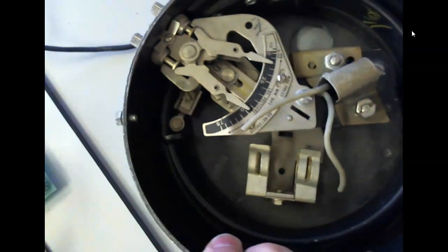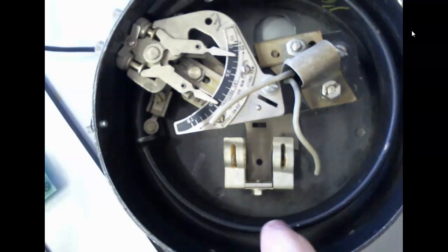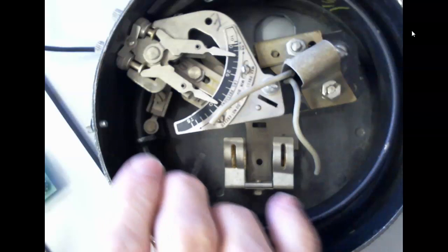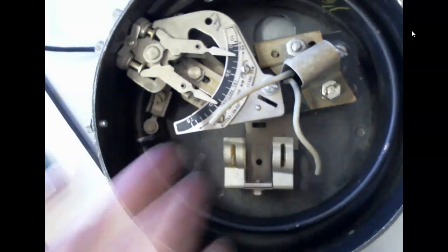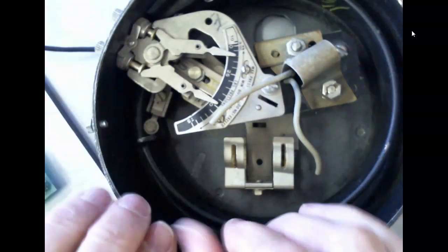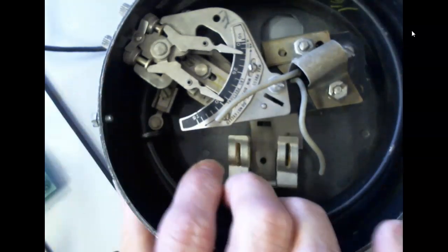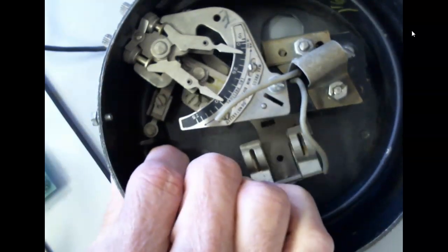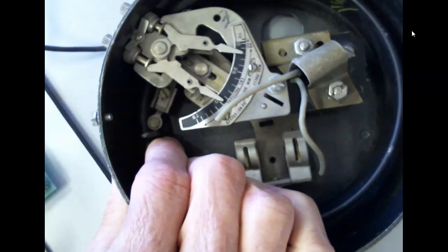What happens when the pressure comes into a helical bourdon tube is it would try to make it come out of the helix, unwind. A bourdon tube, by the way, can measure both pressure and vacuum. If we put a pressure on it, it's going to cause the bourdon tube to try to come out of that C that it's in. If we put a vacuum in it, it would cause it to try to contract, right? That makes sense. So we can use bourdon tubes to measure either a positive pressure or a negative pressure, which would be a vacuum. Everybody okay?